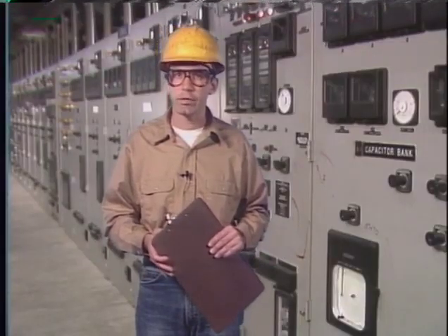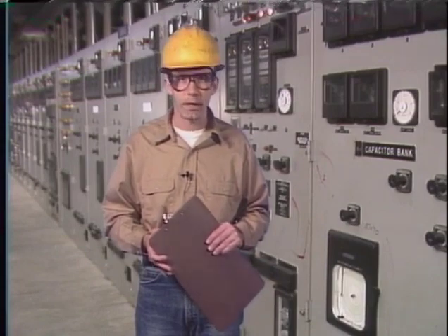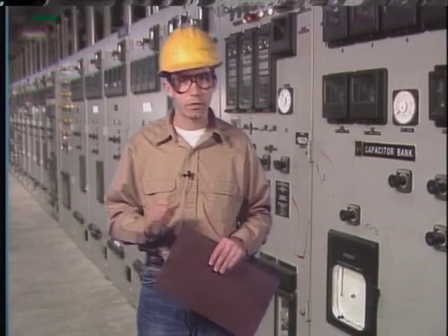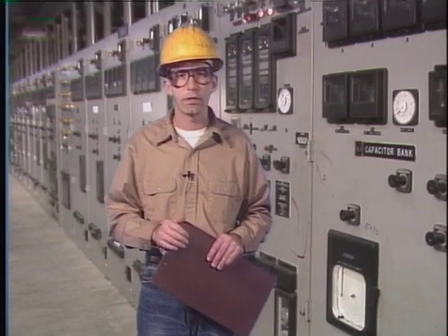So for both air magnetic and vacuum breakers, their protective cabinets are inspected and cleaned, and the breaker bus, line, and control power connections are inspected. Then, in addition to the general checks, specific checks for air magnetic breakers include inspecting the arc fins, arc runners, and contacts, and checking contact adjustments and puffer operation. The specific checks for a vacuum breaker include discharging the mid-band ring, cleaning the vacuum bottles, and checking an erosion indicator to determine the amount of contact erosion inside each bottle.